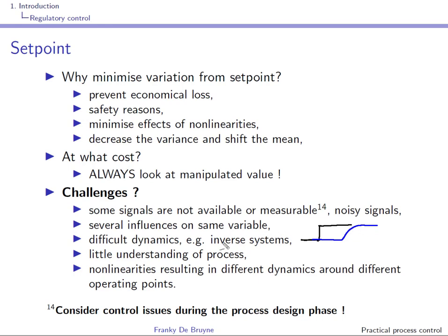And of course, if you have an inverse response, something that looks like this, well, this will of course make things even worse. And inverse responses are linked to the zeros that are to the right of the imaginary axis in the Laplace domain.